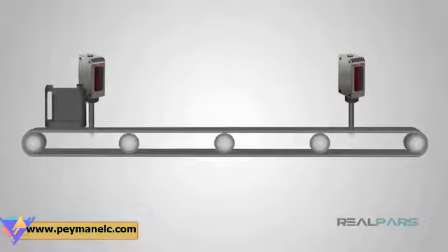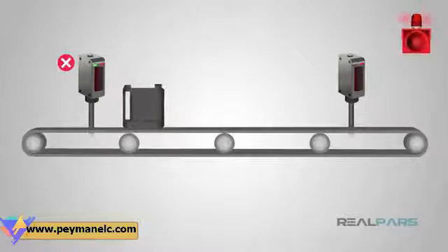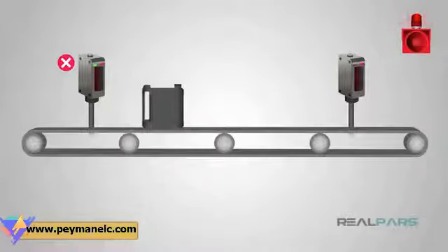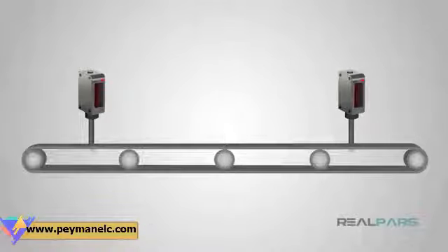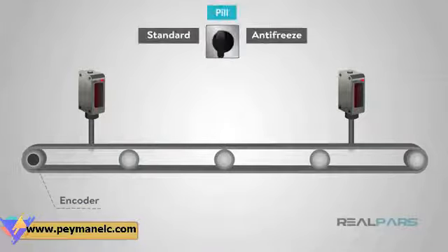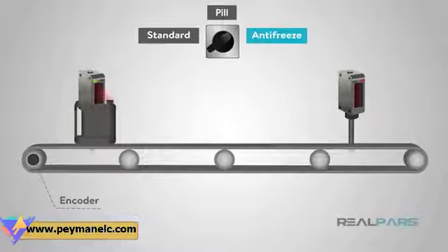How about the antifreeze bottle? Bottle in, cap passes in front of an entrance sensor, bottle counted, then the handle. The system faults because it sees a blockage at the entrance. How do you tell the machine that this is expected behavior? An encoder, of course, and a selector switch for a setup mode. To set up, insert your product, in this case the antifreeze bottle. You make sure to feed cap first, and it must contain a foil.